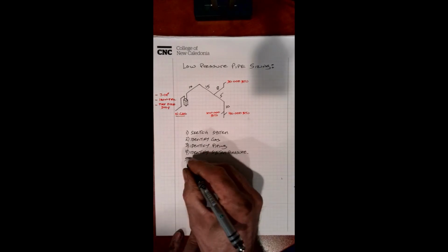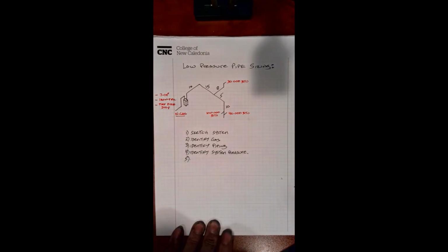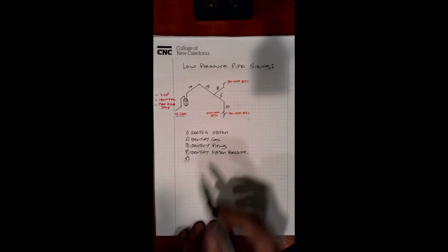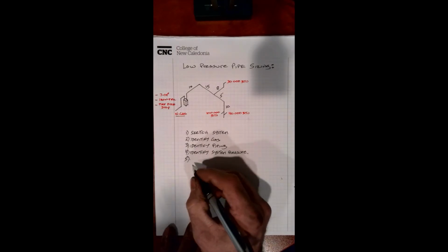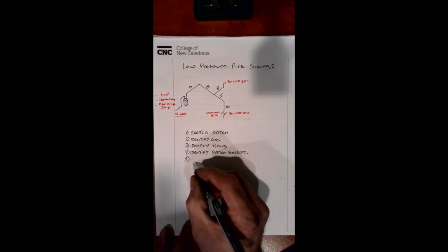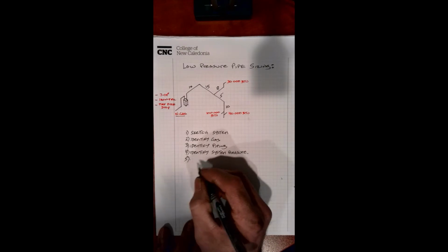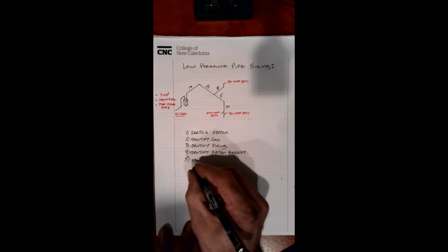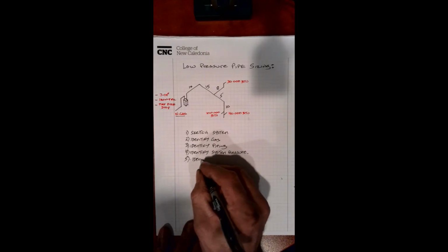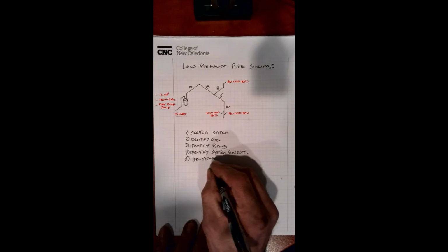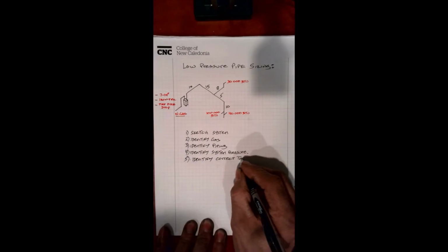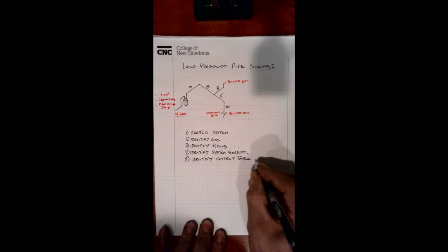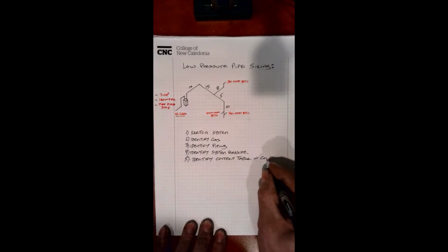Okay. Step 5, we're going to select our correct sizing table based on the information that we've got in our first 4 steps. But for now, let's go ahead and write all the 9 steps so we can go over this in a methodical way. So step 5, we're going to identify the correct table in the gas code.